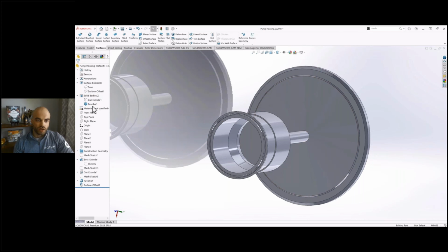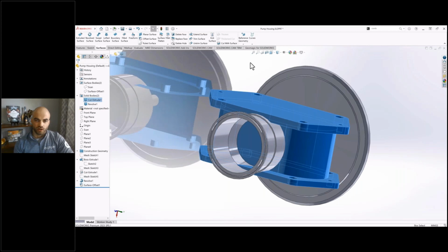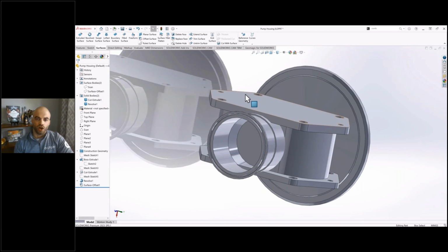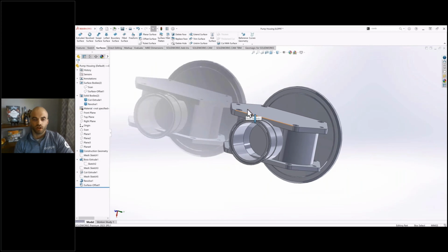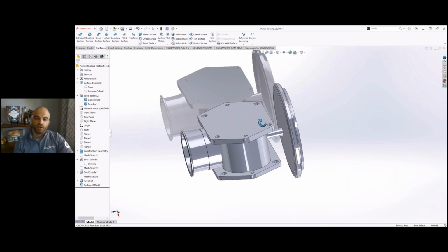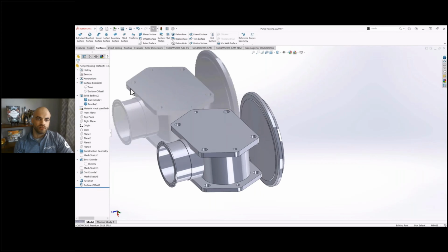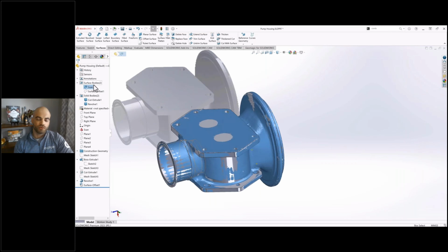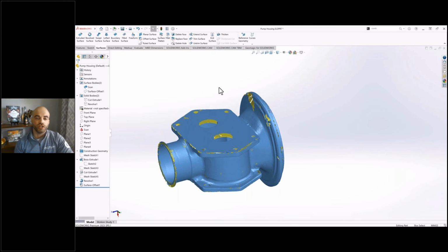So you've got those first two main features, and we're going to start looking at our third feature, which is our lofts, or our loft and our loft profiles. Now for lofting, what I'm trying to do is put my cross sections at areas of changing curvature, transition points.